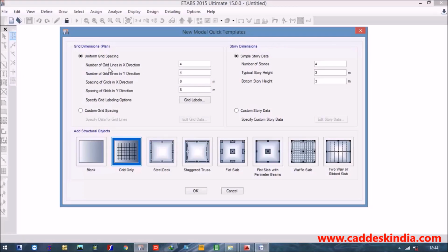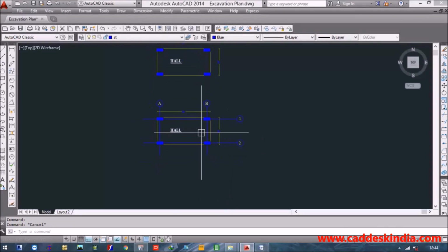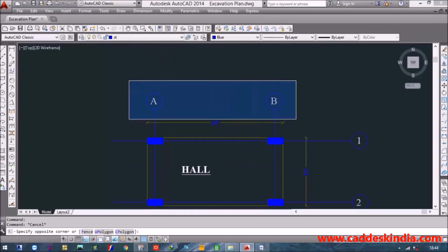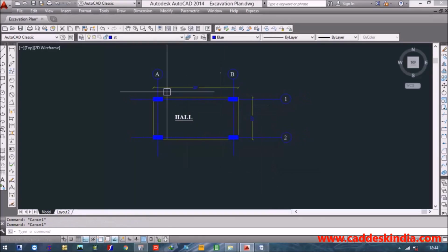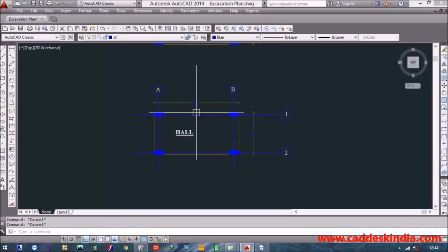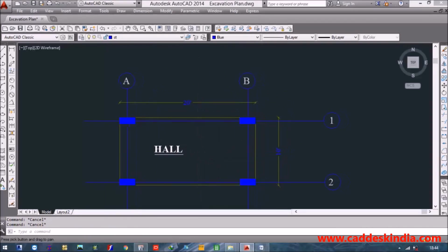First, to set the plan: ETABS is basically a software that is used to perform analysis and design in engineering, and it is based on the grid system. So first, you just prepare your grid in the X and Y direction, and draw the grids in the ETABS software.